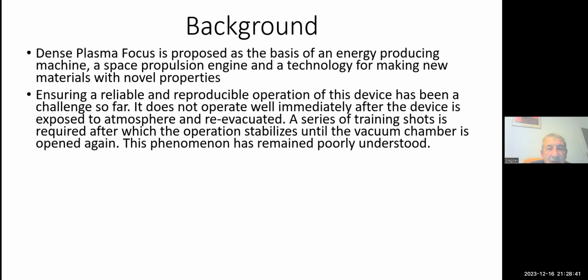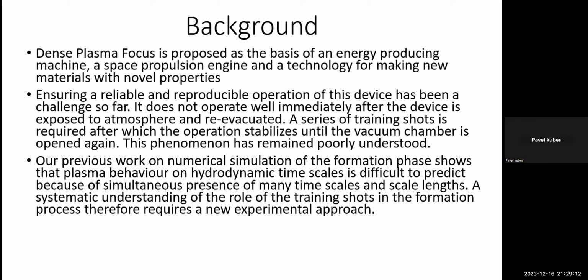It does not operate well immediately after exposing the PF machine to the atmosphere and re-evacuating. A series of training shots is required, after which the operation stabilizes until the vacuum is opened again. This phenomenon has remained poorly understood so far.